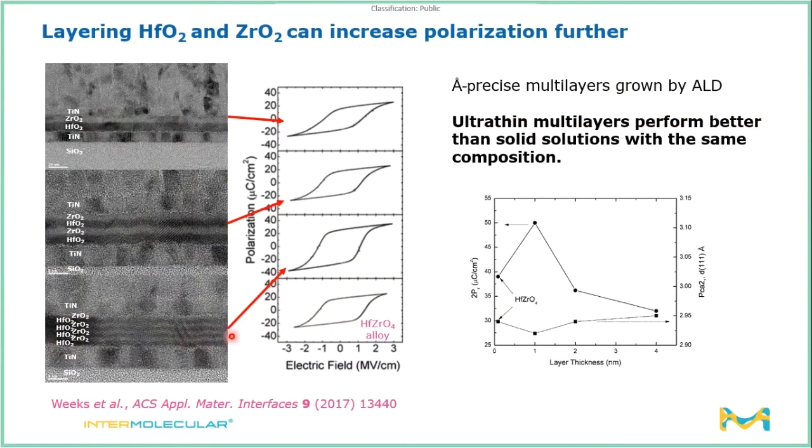And so, again, using that mechanistic insight to understand which order to put the films down in and then going further with experiment to figure out how to tune those conditions, we were able to make ultra-thin multi-layers that showed better ferroelectric performance than solid solutions.